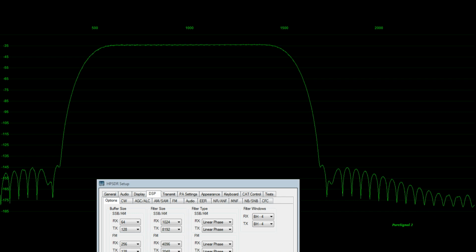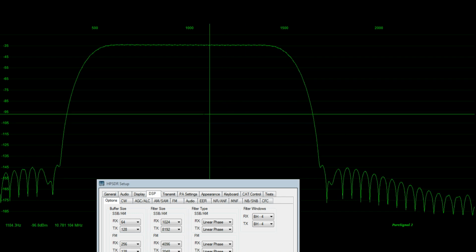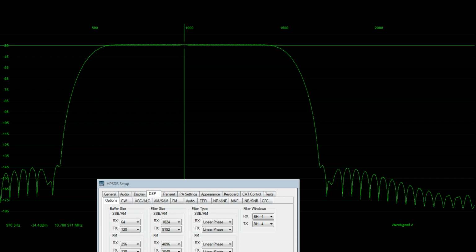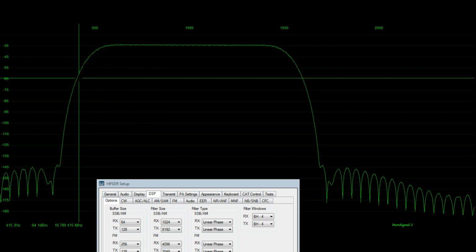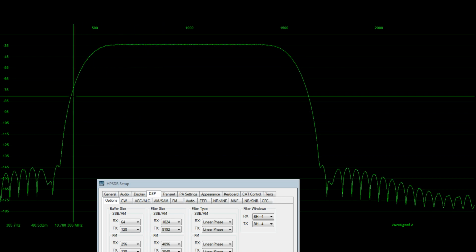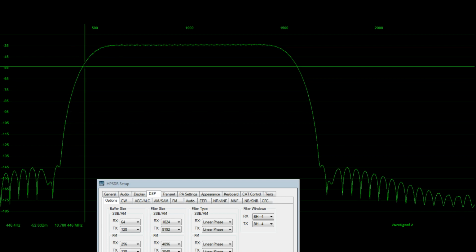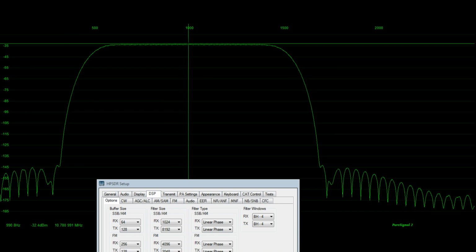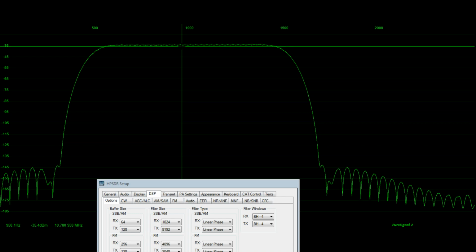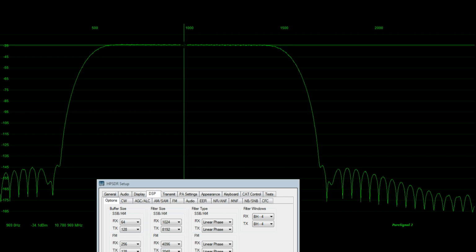Now, going forward, it's also important to mention that if you look at the lower left-hand corner of the screen, you see some coordinates. Those coordinates are how I came up with these measurements. We'll be using these to calculate bandwidth and the actual amplitude skirt of the filter. Also, we're going to be noting that the 0 dB reference is minus 35 dBm on the analyzer. So that's also important to note. Going forward, our 0 dB reference for our measurements is actually minus 35.